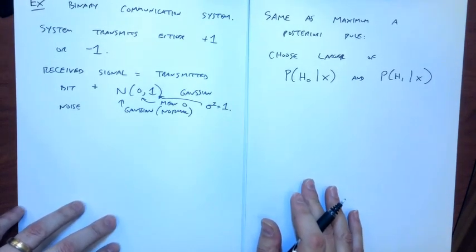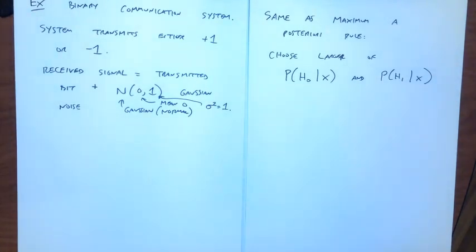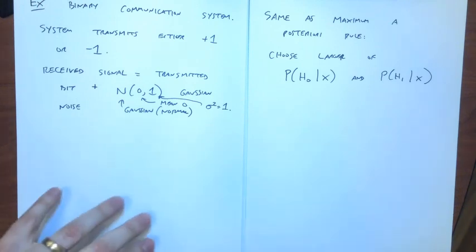And so what I want to do is send bits across the channel, and be able to decide on their side, was this a +1 or was it a -1, right? Now, if there's not that much noise, then the +1 and the -1 look like little Gaussian distributions on their own, but if the noise is large, then those distributions could overlap, and if I get a signal that's like 0, it's like, well, is this a +1 or a -1, right? So I have to make that decision, I have to draw the line somewhere, right?